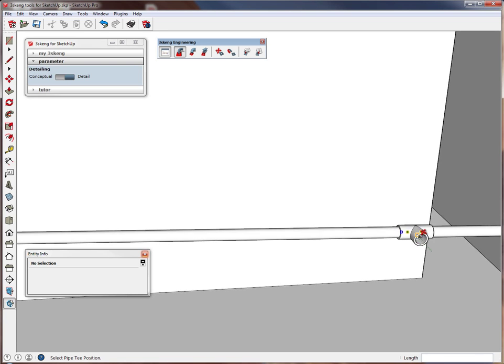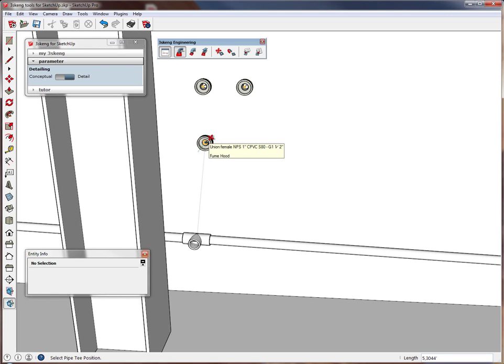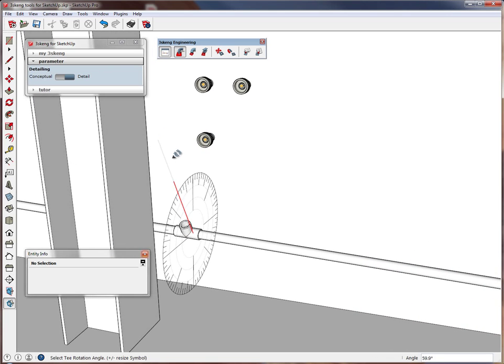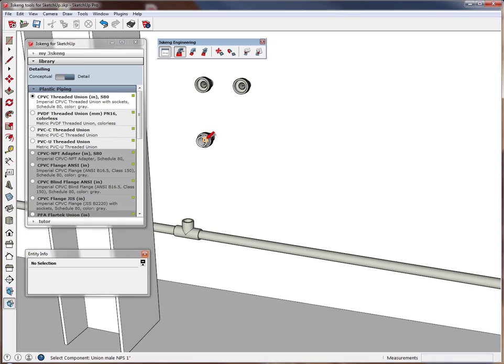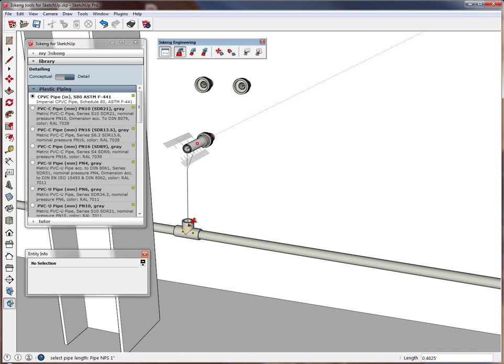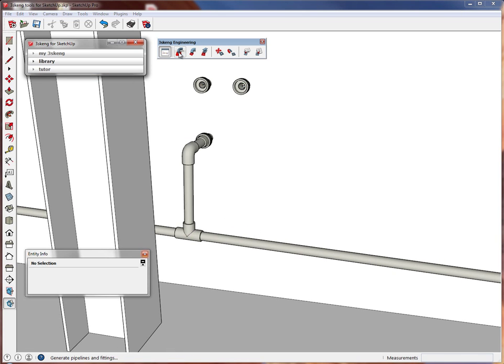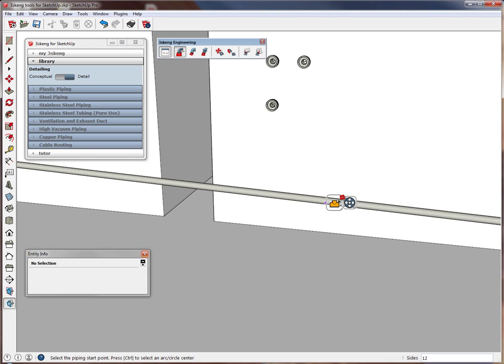When we pick it, we are asked for the final connection, and we will pick the reference to the female union. Have it face upwards. Now we have to apply the counter union and can use the auto pipe function of the detail to get the available connections with 45s and 90s. We have to do the same for the two other connections.